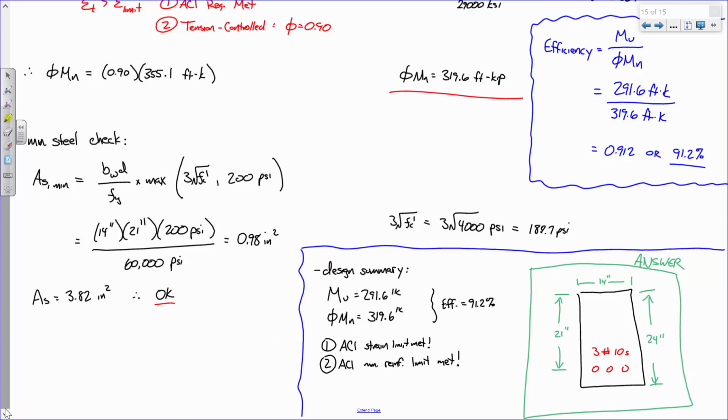What if I told you couldn't change that? The area of steel had to stay the same, the beam width had to stay the same, the beam depth had to stay the same. There's 2 more. There you go. What's the other? The grade of steel. Boom. Exactly right. Those are the parameters that are going to affect how strong the beam is.